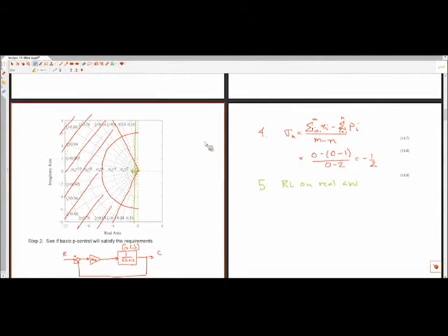So the lines give us all the possible closed loop pole locations as we vary this parameter. In this case, it's the proportional gain from 0 to infinity, right? So that's for all possible options of proportional gain. And so what this is saying, green doesn't show up too well, hope you can still see it in the back. What this is saying is that when k is low, the closed loop poles are going to be very close to the open loop poles, so somewhere in here.